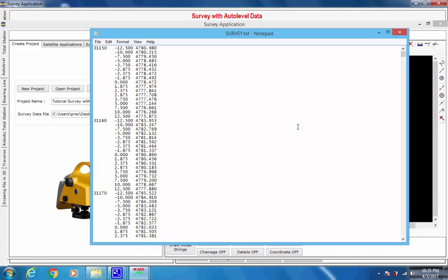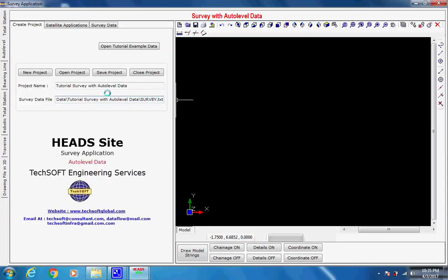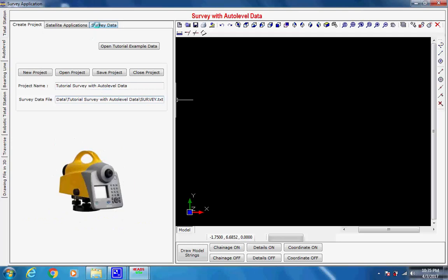The data do not have easting, x, and northing, y, at these points where, z, is available. So, to get easting, x, and northing, y, at these points an alignment is to be defined, which passes through the center point at 0.0 of each cross-section. Referring to this alignment, the program will obtain the x and y coordinates of each point on the cross-section. This helps in making triangulation, digital terrain model, and finally the contours of the ground.